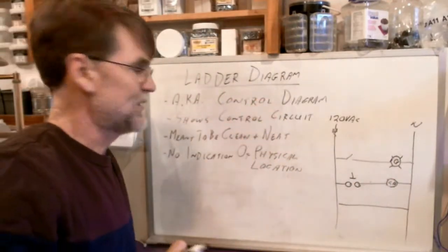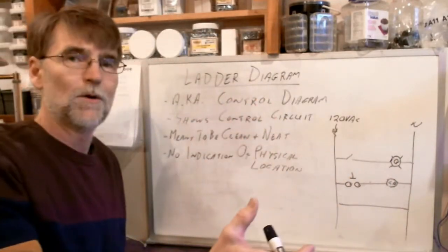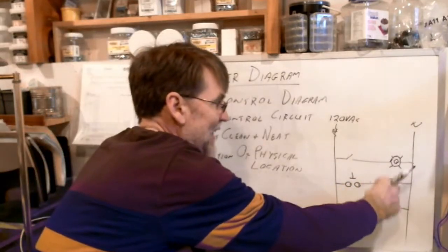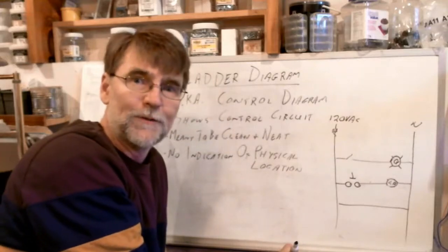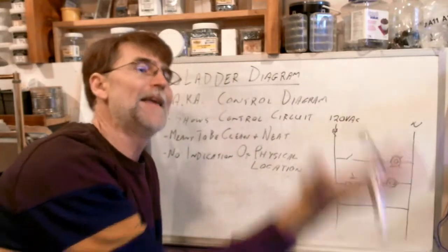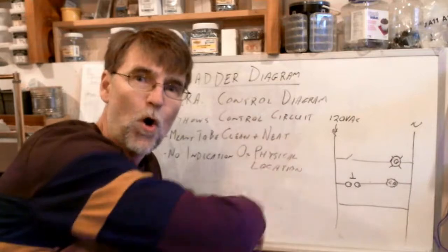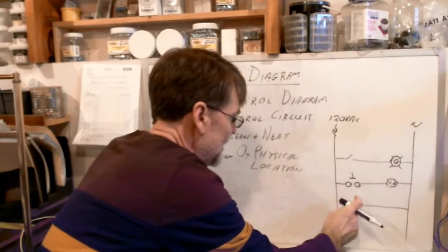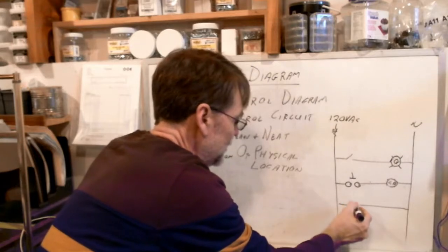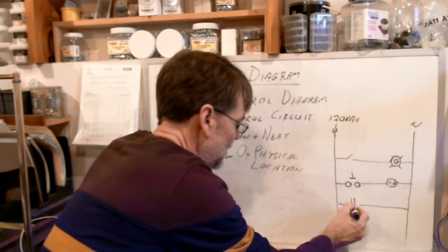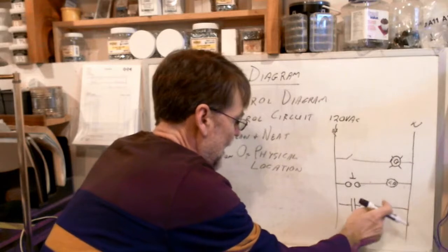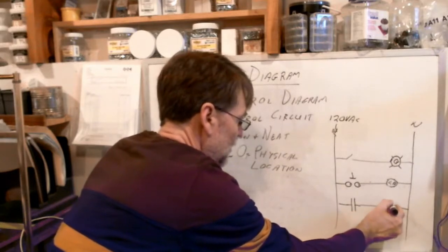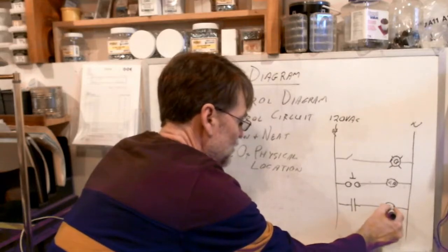And a cube relay, that was the thing that, well, I call it a motor starter, but a cube relay functions in the same fashion. We can create that magnetic field by putting current through that coil, and it will pull levers open or closed. It will toggle contacts. So down here on the next rung, I could draw a normally open contact, and right here, now I draw my red light.